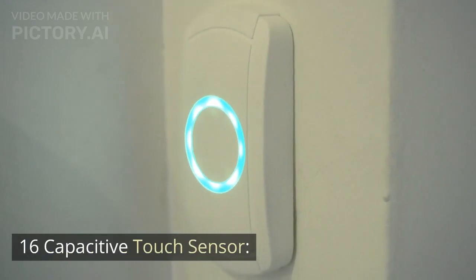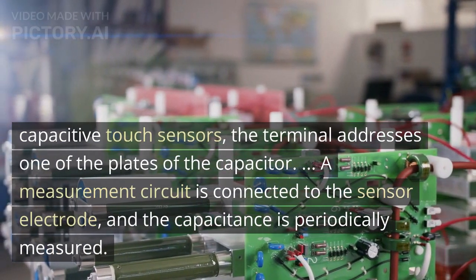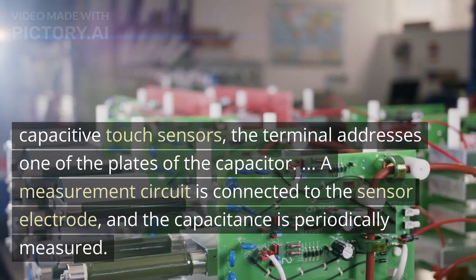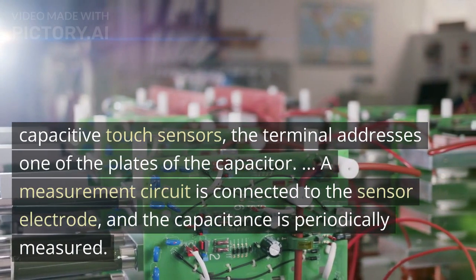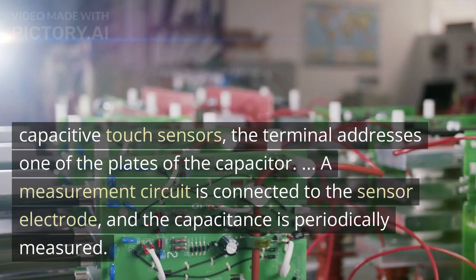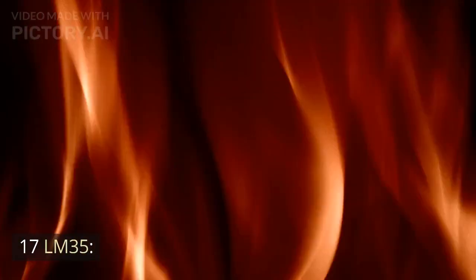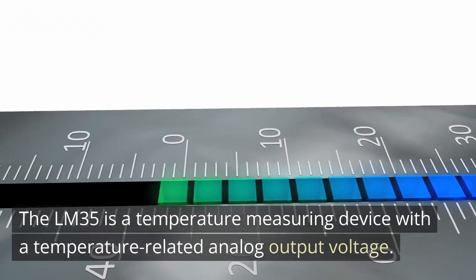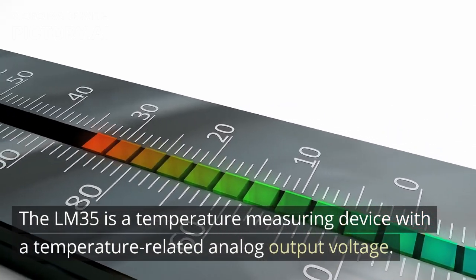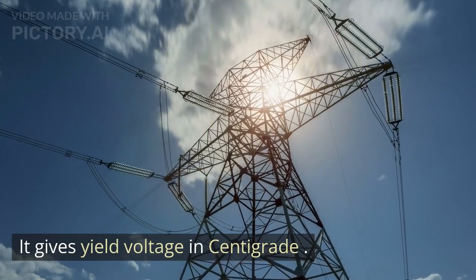16. Capacitive touch sensor. In capacitive touch sensors, the terminal represents one of the plates of the capacitor. A measurement circuit is connected to the sensor electrode, and the capacitance is periodically measured. 17. LM35. The LM35 is a temperature measuring device with a temperature-related analog output voltage. It gives output voltage in centigrade.